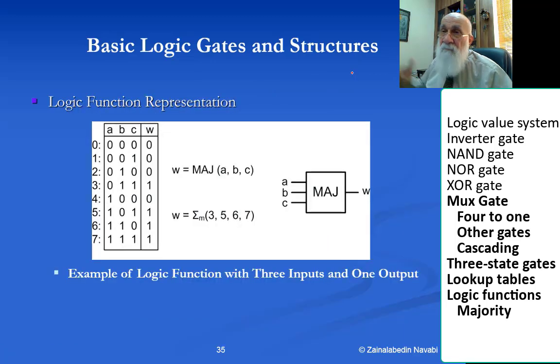And a majority gate is also a gate that in a lot of cases I can assume I have the gate level structure of. I can build a majority gate using a pull-up structure, a pull-down structure with some inverters maybe. And in the list of our primitives, it's a good thing to have the majority function.